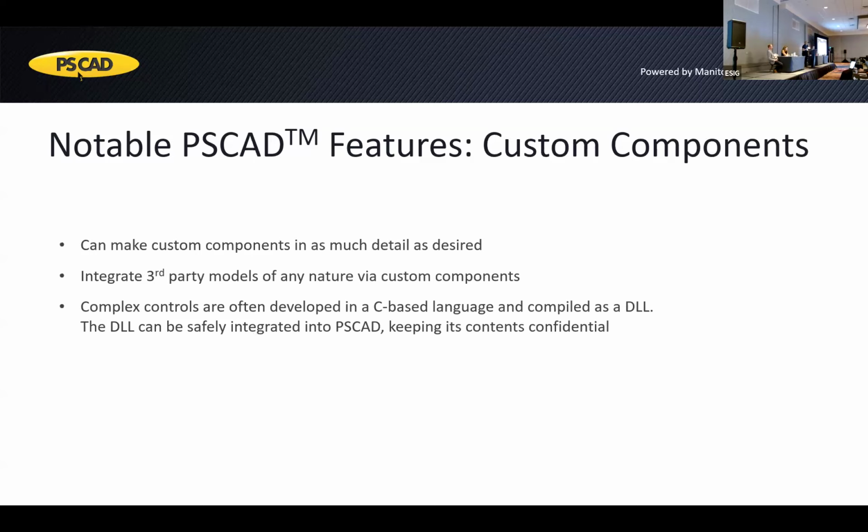Lastly is custom components. You can make custom components in as much detail as you would like with PSCAD. This allows you to integrate any type of third-party models of any nature using these custom components. For example, complex controls are often developed in a C-based language and compiled as a DLL. This DLL would be able to be safely integrated into PSCAD, keeping all of its contents confidential.